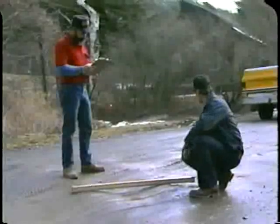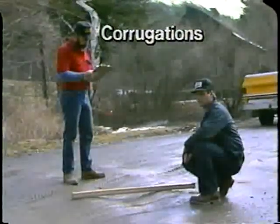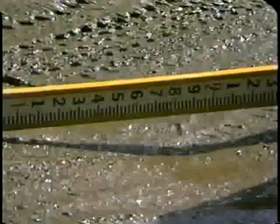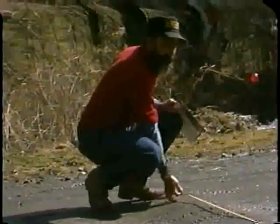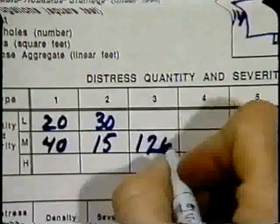Number 3 on the inspection sheet is corrugations, or washboarding. We measure these by putting a straight board across the top and measuring depth. Severity is indicated by the distance between the high and low points of the corrugations. Record the area in square feet at each level of severity. This sample has 126 square feet at the medium severity level.